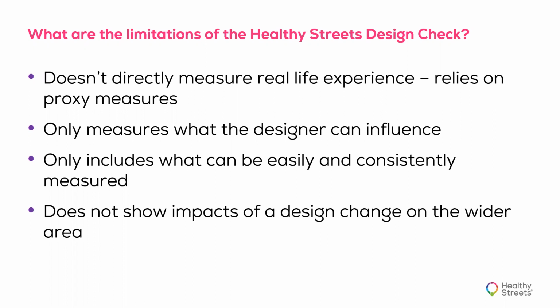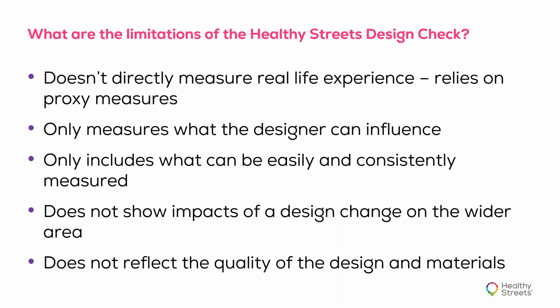So if you're going to be having an influence, for example, on traffic flows, it's important that you're thinking about running that check on all the streets that you think may have a knock-on impact as a result of your redesign, so that you can see whether you're actually resulting in an increase or a decrease in the Healthy Streets Check score on surrounding streets.